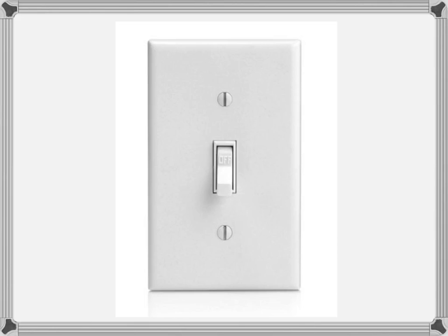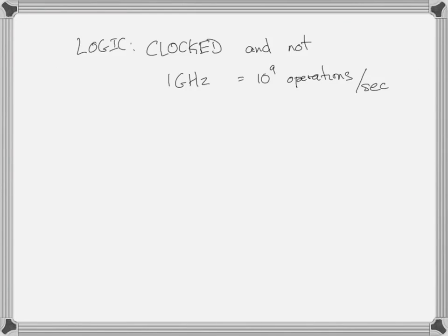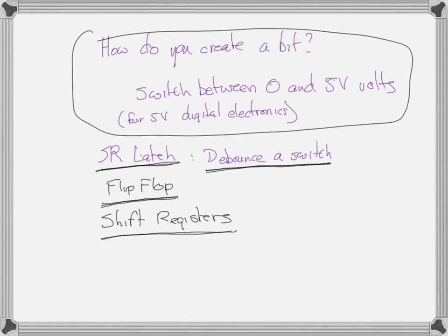They make the electricity before, and we should talk about the time scale. Typically, the time scale may only be milliseconds. With a light switch, you've seen it before. It might be a second before you push it all the way up, probably not a second, but half a second before you make a good contact. But it may be a few milliseconds. For a few milliseconds, it's trying to make good solid contact, and it bounces a little bit between its low value and its high value. So that's really bad for digital electronics. Bouncing is bad for digital electronics.